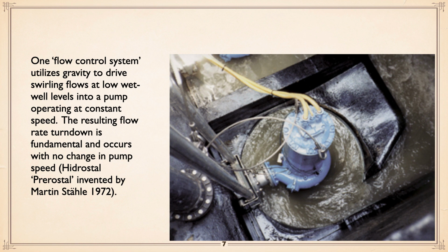This is an interesting little thing that kind of is based on that theory. You've got a submersible pump which is rotating clockwise. If you look down, you can see the cut water just below the motor. And if it goes around in behind, it gets larger and larger. And as it comes in view, larger still and a bit of a nozzle. And that pump is rotating clockwise. But it's in a sort of a wet well at the bottom that when the level is down, like it shows here, there's a clockwise flow induced.